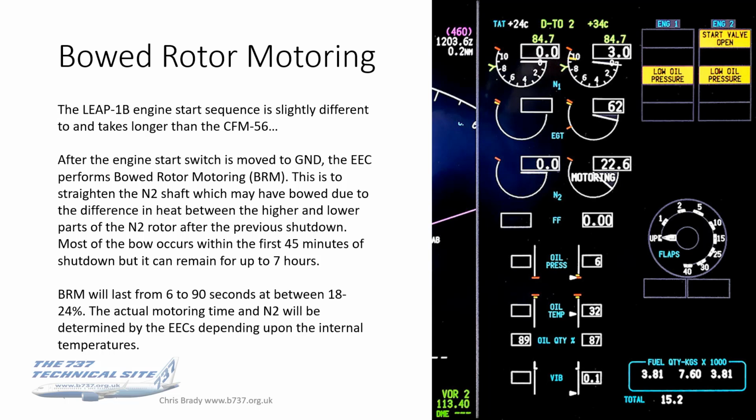All right, bowed rotor motoring. Here it is. This is one of the drawbacks of the Max over the NG. On the LEAP engine, the start sequence is different, and it takes a lot longer to start than the CFM56. It actually takes about 3 minutes per engine, particularly on a quick turnaround.